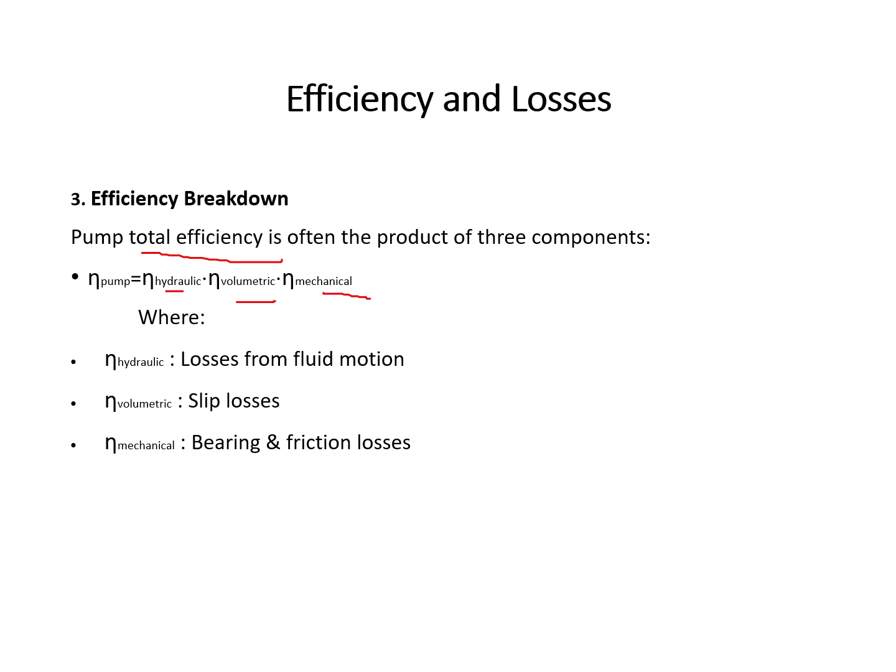So if I want to ask a question, how can we improve the hydraulic efficiency? Try always to use smooth impeller designs that will minimize turbulence. How to improve volumetric efficiency? Always maintain the seal. It should be a rigid seal that will prevent slip.